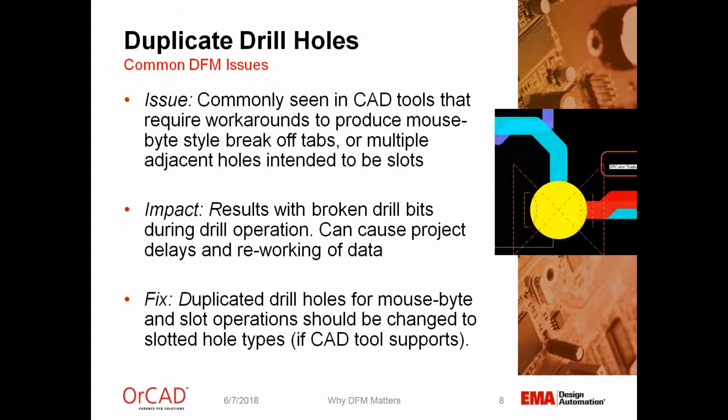And what happens as far as the manufacturer is concerned is this results in broken drill bits during the drill operation, because it's a high-speed drill. And this can cause project delays because they may send your data back to be reworked. The fix for this one is, we don't have to do duplicated drill holes for slot operations. These are fully supported in our tools today.